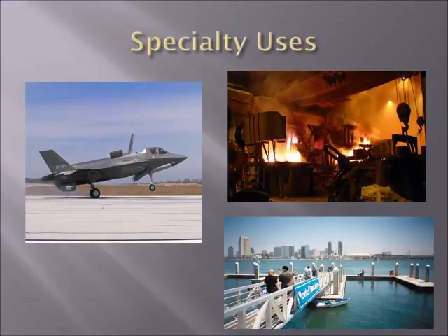One last application I would like to touch on is what we call specialty uses. These concretes are going to be exposed to harsh environments, such as F-35 vertical takeoff and landing concrete pavement, refractory concretes, which are exposed to high temperature, and concrete docks or piers, which are exposed to harsh marine environments. Structural lightweight aggregates and structural lightweight concretes have been used for years in these applications. They perform very well. Much of this is due to the aggregate's properties and the cement paste properties being very closely related, having very similar coefficients of thermal expansion and an improved contact zone between the two.